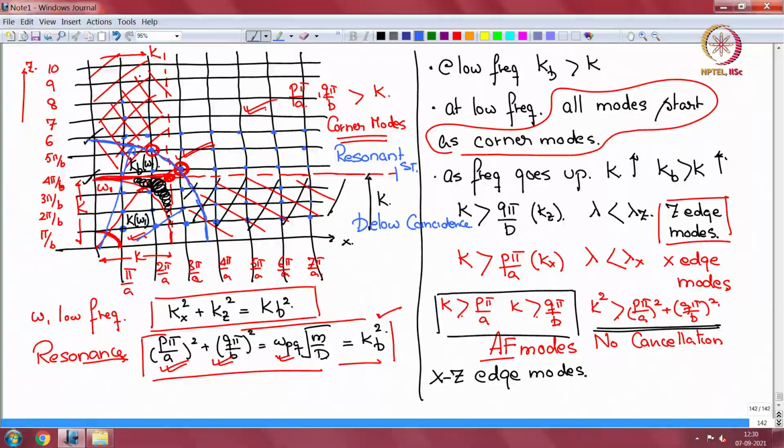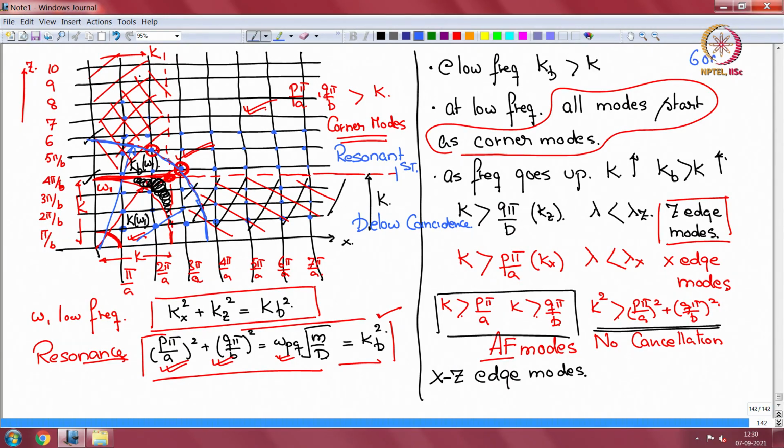the coincidence frequency for most thin panels is in the range of 6 kilohertz. In that range, okay, it is inversely proportional to thickness. So thicker panels will go down. Of course, thicker panels are hard to excite and are poor radiators by themselves. So we will take 6000 hertz as some kind of number for steel. Okay, so mechanically it's very hard to excite that frequency. Okay, mechanical excitations usually don't come up that high unless you have cavitations or explosions or something like that.